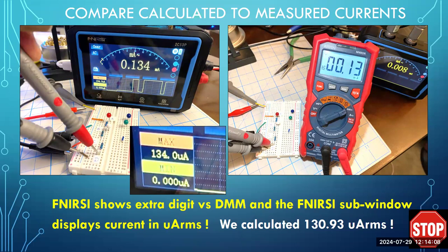If you look at the probes as they touch into the circuit on the left, I created an open between the last resistor and ground, and the probe of the ammeter goes into that position. The tablet being used as a multimeter has the BNCs connected to the right side of the device. And so the display shows a fraction of a milliamp, 0.134 milliamp.